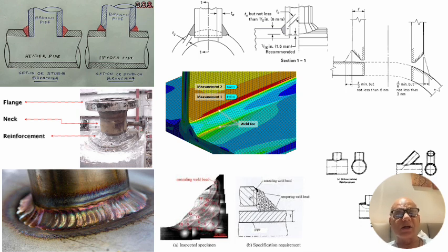Ultrasound and X-ray in a fillet is not easy like in a butt joint. Very carefully we have to do this test. A qualified person who has experience can only interpret it very well. Otherwise, as we saw in the earlier case, the root gap which is seen here may reflect as an indication for a fillet defect.